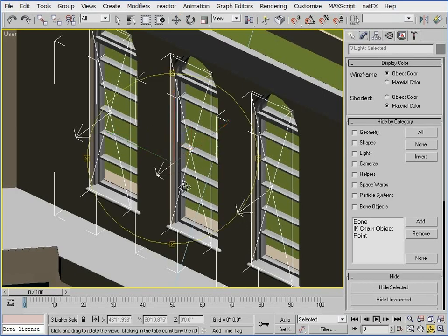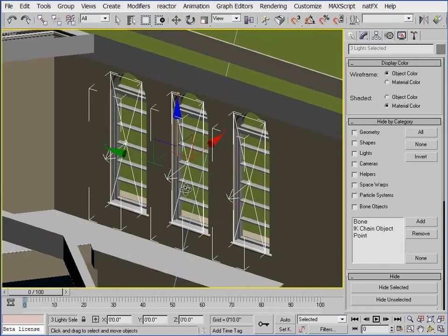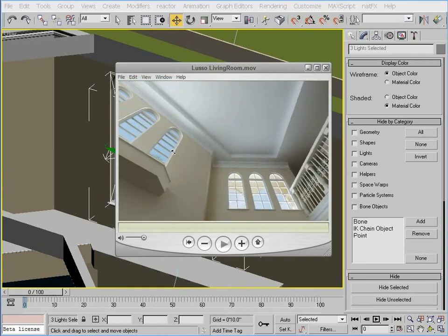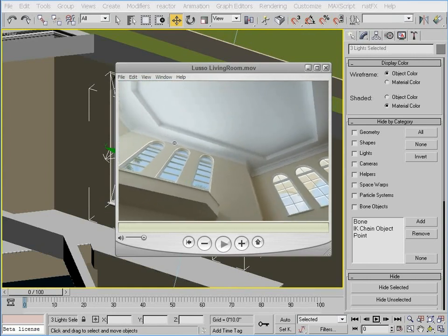If I did this for a light on the inside, you might see the same amount of illumination all along the top boundary of the light bouncing onto the ceiling, instead of seeing light brighter in areas right in front of each window, which would be more realistic than seeing the same amount of illumination all across the top, even in areas where there's no window directly below the ceiling. So in this panorama, it looks like the same amount of light is shining all along the ceiling. It's probably not necessary to create 3 individual lights, but as a matter of rule, I like to take the few extra seconds to do it.